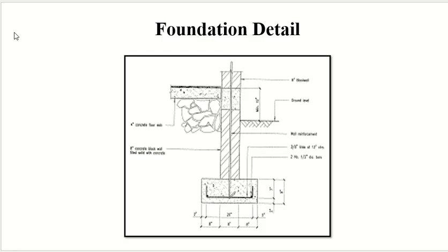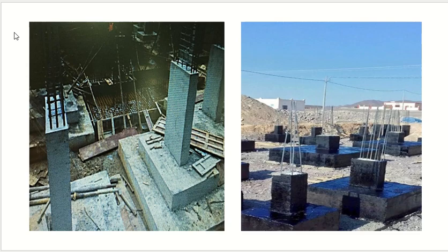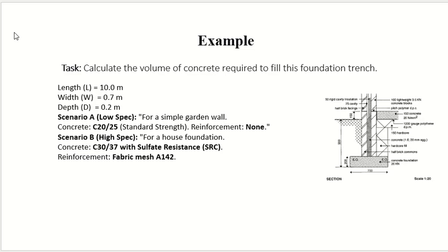But if you look at the column, you will tell me, okay, from here to here, one steel bar. No, your calculation is wrong because you are not considering the steel of the column inside the foundation. Got the point? Clear? Good. And you can see the dimensions as well. These are some real foundations.